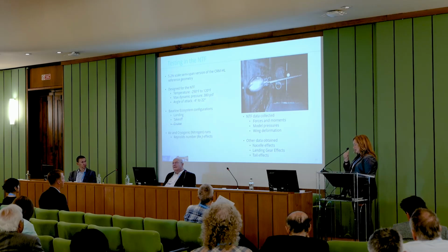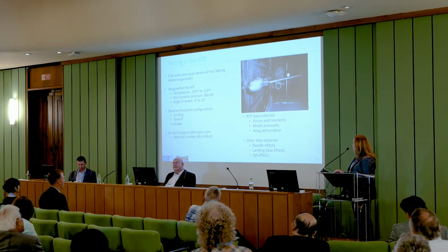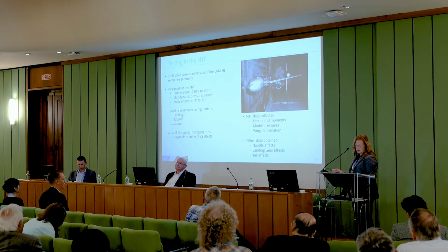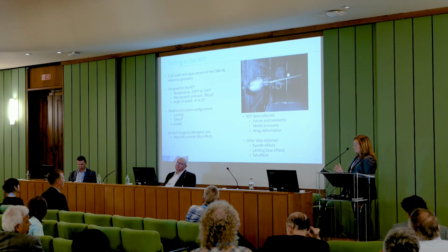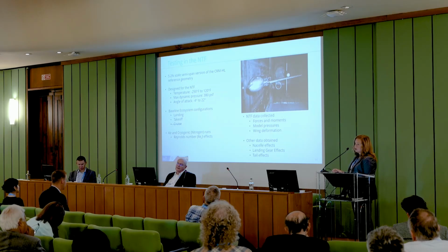Okay, and then finally, we were ready to test in the NTF. The schedule finally was able to accommodate us. So this model, as I said at the beginning, was designed for the NTF, so it can withstand temperatures from -250 Fahrenheit to 120 Fahrenheit, a maximum dynamic pressure of 380 PSF, angle of attack -4 up to 22 degrees.